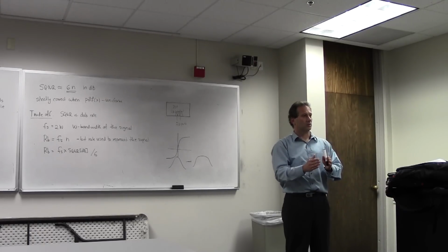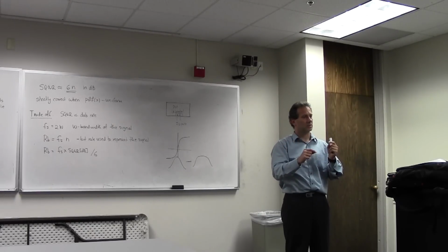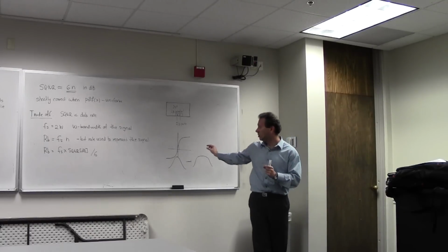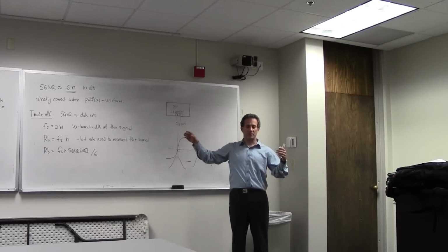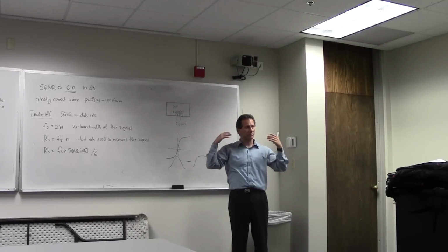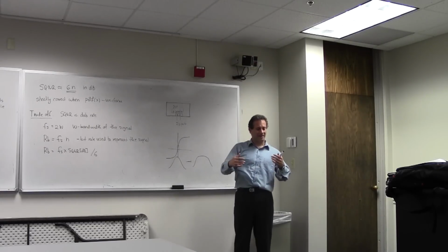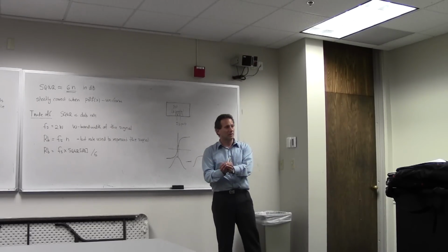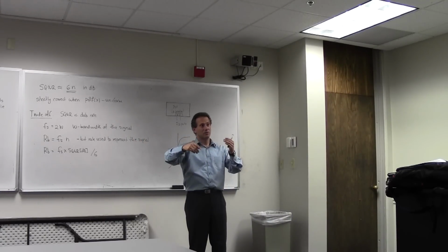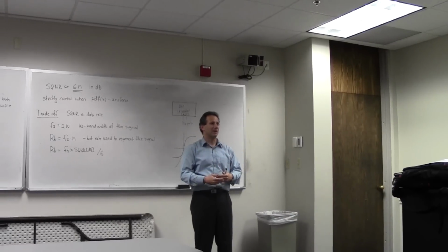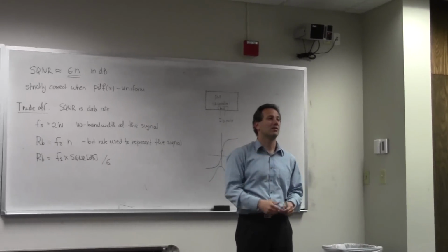So that's not good. So what we do is we say, okay, before I quantize the signal, I'm going to amplify it with something that's nonlinear, and take these small values and make them large, and take these large values and pretty much leave them on their own. And what that does, it restores the signal. If you play that back to your ears, it's going to sound really funny, right? But it's good for a quantizer. The quantizer would introduce less of an error there, and then you would send that to your system. But before you play it to the user, you have to do the inverse operation. You have to decompress, right? And then the overall net effect of that is that you improve the SQNR for the whole system.